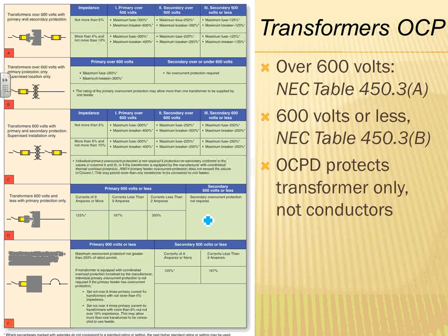Now moving into the installation of transformers, so I thought this is a summary of the NEC code book, guys, the overcurrent protection device. For transformers, when we size the feeders for the transformers, the primary feeders or the secondary feeders with transformers. When we size a feeder, guys, the question that you're going to ask yourself is, is it a continuous load on this transformer? If it's a continuous load on any feeder, how do you size a continuous load?